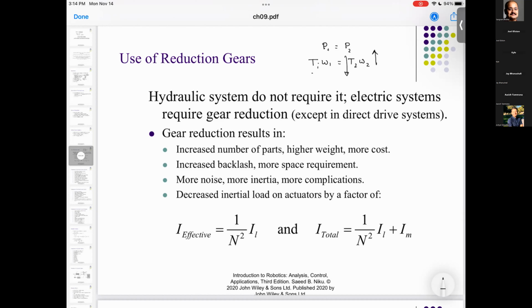Just like you have a car, and if you are driving stick shift, then you start the vehicle in neutral, then put the vehicle in the first gear where the speed is low, torque is high, put the vehicle in the second gear where speed is medium, torque is medium, and then you put the gear in the third or the fourth gear where speed is high. So the vehicle picks up speed, but the torque is low, which means if you have to climb a hill,